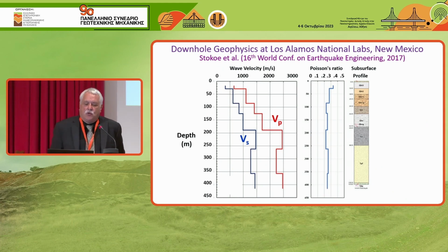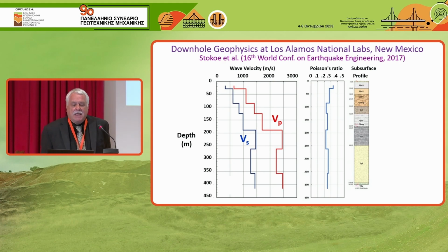And the profile looks like this. This is Stokoe's interpretation. It's typical to show steps. I personally don't prefer the steps. I prefer just to show the midpoint as a single dot. But the convention is to show the steps where they take the changes in the slopes. But in this case, you can see the 2 velocities with depth, and they're going down quite deep, 400 meters.